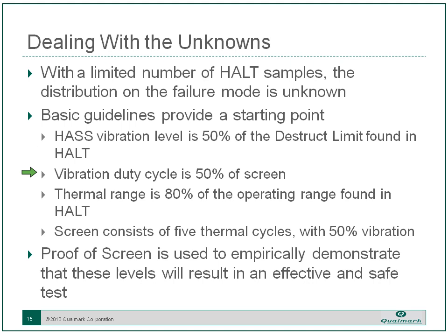And typically we'll begin by running a vibration duty cycle of 50% of the screen. So half of the screen the vibration is running, and that vibration is running at 50% of the destruct limit. The thermal range that we go over is 80% of the operating range that was found in HALT. So it's guard banded, but not by a whole lot. And then we'll build a screen that is 5 thermal cycles with 50% vibration running during those 5 thermal cycles.